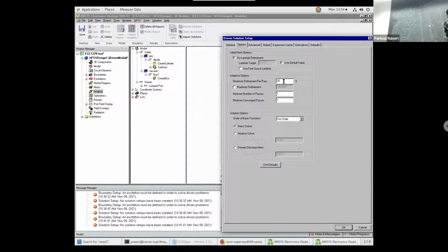This is the same geometry, right? Now, if you say only, for example, change 30% or improve 30%, since you only have 2 mesh cells, 30% of 2 is 0.6, right? 0.6. In pass number 2, it tries to only change one of them at most.